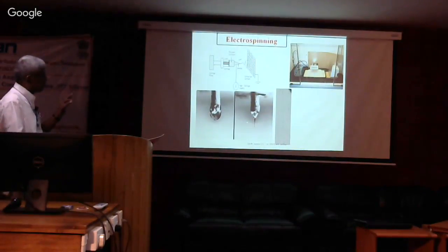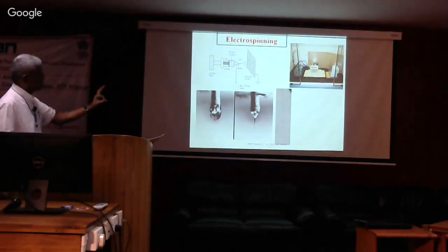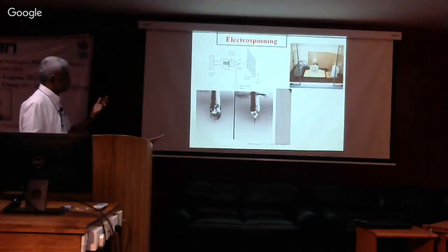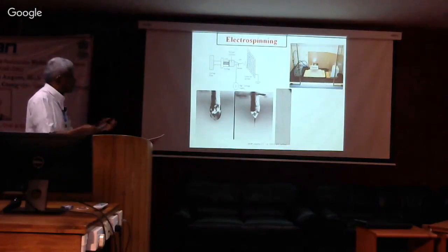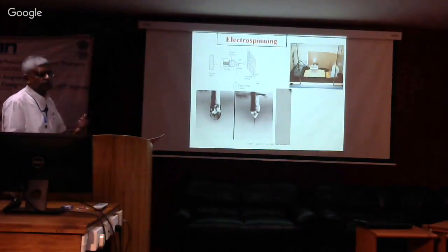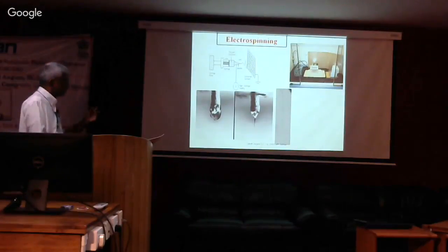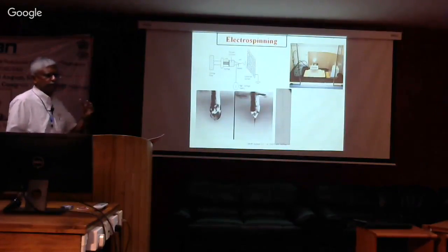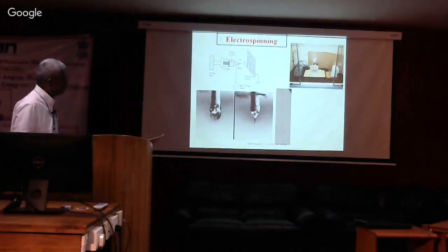What you see at the tip is this stretched mixture, and as it leaves, it gets more and more stretched. As I said, the trick is to design the system such that by the time it leaves here to the time it gets here, the solvent evaporates. So you get this pure fiber, pure meaning just the polymer.